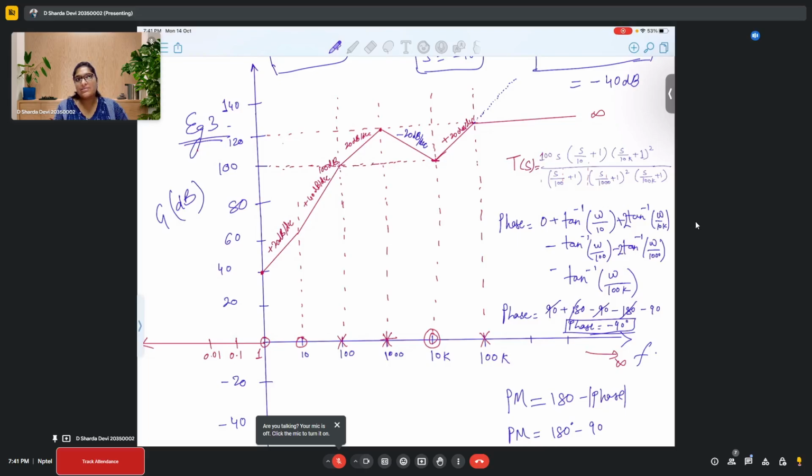So the answer is, whenever we are designing some systems, we focus on the number of poles. We also try to minimize the number of zeros, because zeros are not much of use to us. It's just when we have to compensate that we introduce zeros, but rather we want to have only pole based systems.